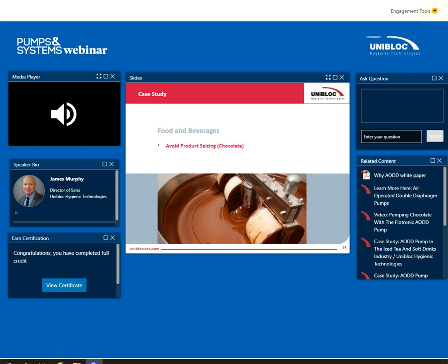The big challenge is draining. Now that we've introduced this product and filled the entire pump with the cleaning agent, how do we get it out? Traditional figure eight designs typically are on a swivel stand, so the operator would have to swivel the pump in a 360-degree motion so that it would drain out all the product. The other design, that center design that I've referenced, actually has a small channel machined into the seat. So now the pump is self-draining, and you don't actually have to rotate it. It takes roughly 15 minutes for that CIP solution to drain out of the pump itself. So they are 100% CIP-able.